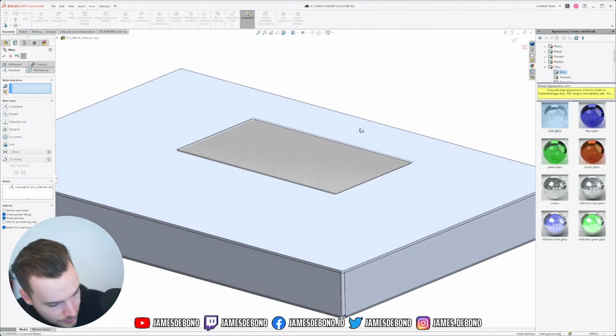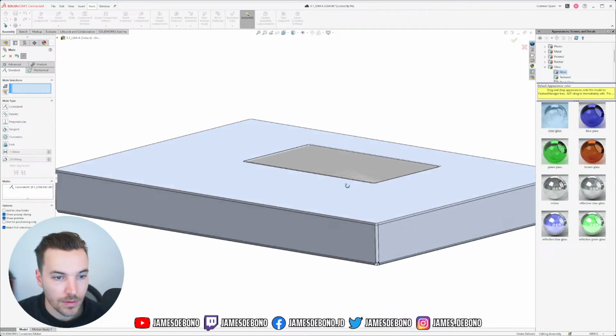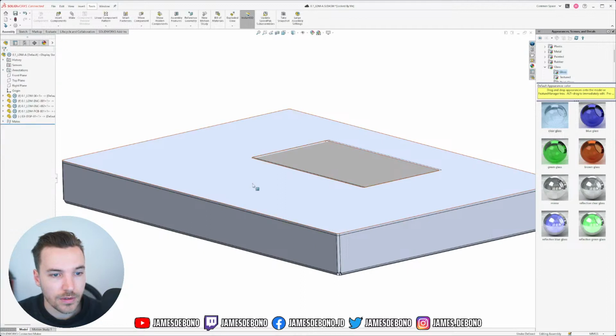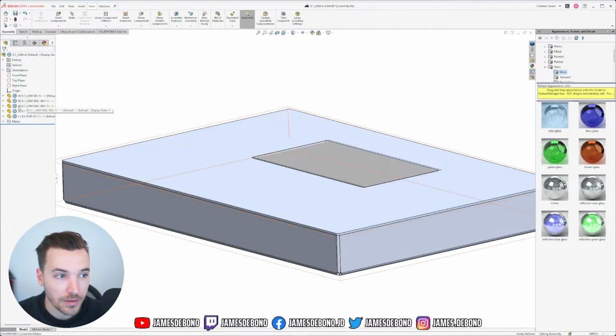But the problem is, if I made it to this top surface, like to this part, it might be that I delete this part, or that I get rid of this part and replace it for something else, or I make a new part, or I make a different version of this part and I want to swap them out or something. And as soon as this part's gone, then that mate is gone, or that mate will fail.